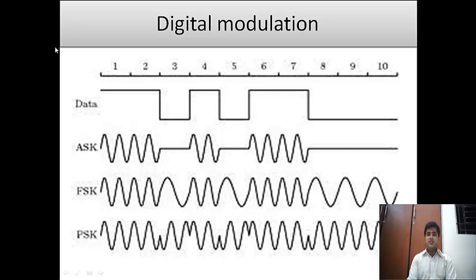There are various factors which I want to discuss. Various factors should be considered when choosing a particular modulation scheme for a communication system. A modulation scheme should be spectrally efficient and possess a low bit error rate (BER). It should have low error, especially at low signal to noise ratio.